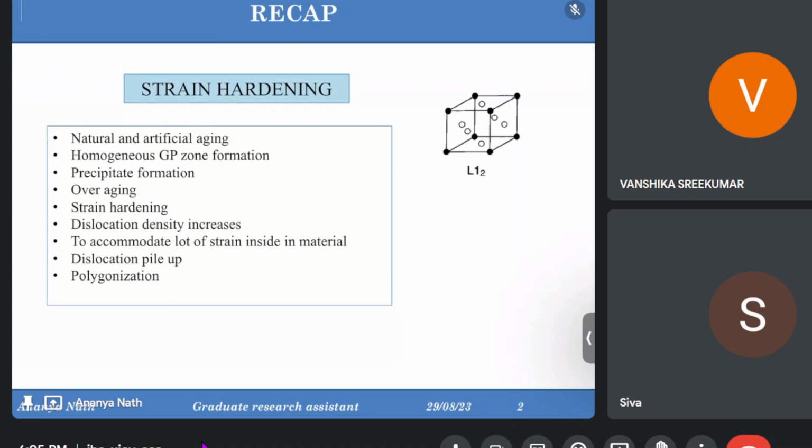But for non-heat treatable alloys, we can do these things, but those alloys will not really act differently. Those alloys will not get that much increase in hardness if we do the heat treatment. This is why they are called non-heat treatable. So for them, we take help of other processes by which we can increase their strength. One of those processes is cold working.